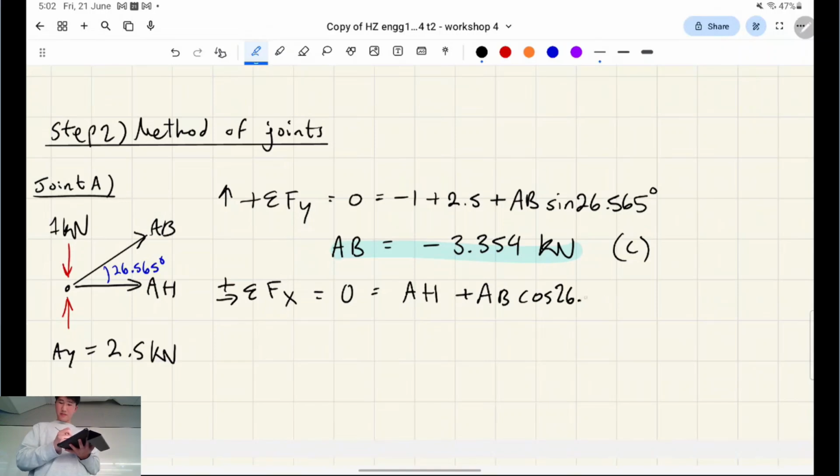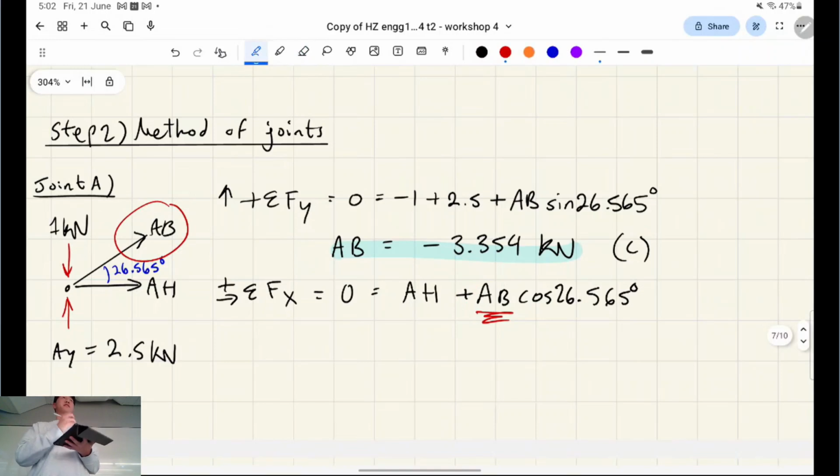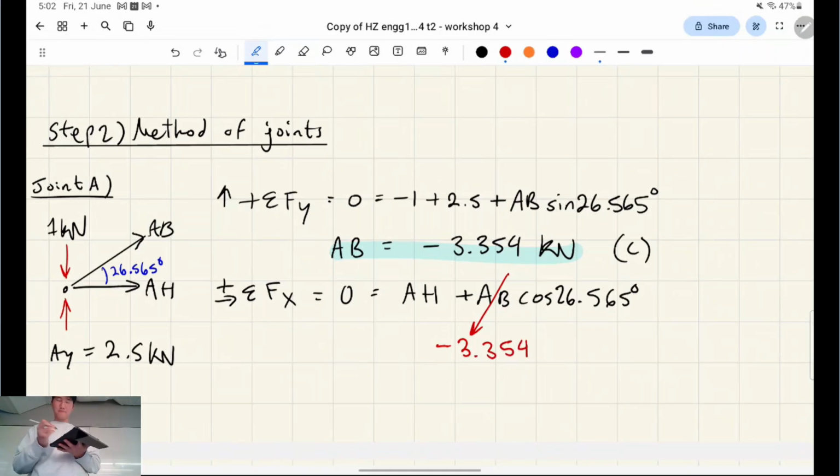Yeah, so I'm going to slow down after I write this line. Because my arrow is going to the right, I'm still going to add on AB and that horizontal component. That's where I'm saying with the double negatives, keep that direction of the arrow consistent. Otherwise, you're going to start tripping yourself up. To account for the negative compression magnitude, when you sub in this number, plug in that negative number, and you'll get the right number. I said number like 3 times, but you get the idea, right?